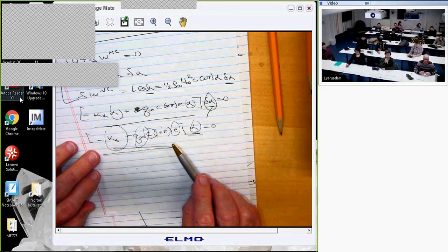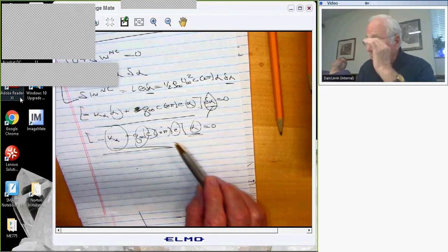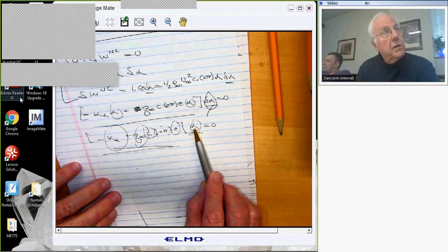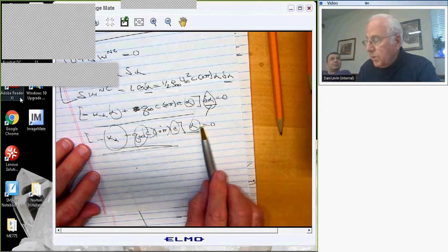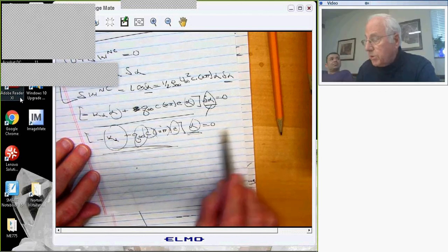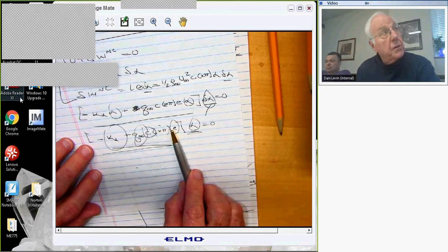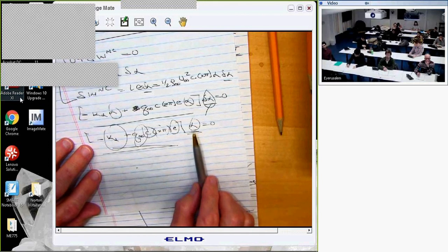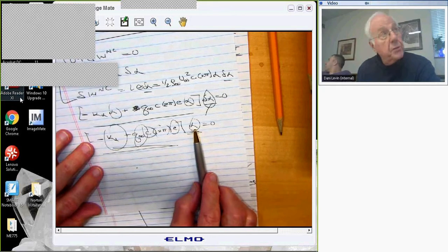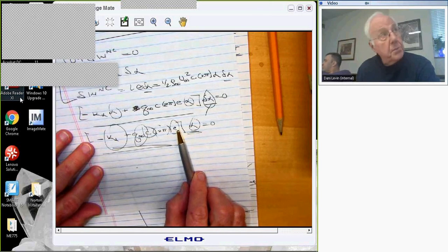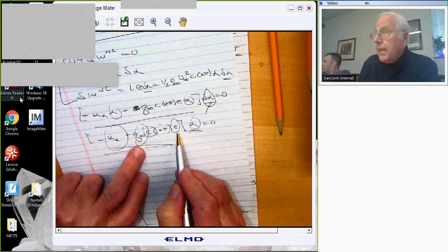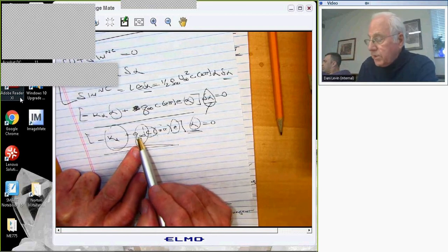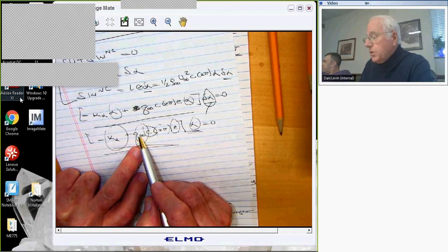What I mean by an eigenvalue problem, an eigenvalue problem is where you have some measure of deformation or response of the system. In this case, it's alpha. And then there's a coefficient that multiplies it. And an eigenvalue problem is when, if you will, the right-hand side of the equation is 0, and there are two possibilities. Either alpha is 0 or the coefficient is 0. And the eigenvalue problem is when you consider the case alpha, or the deformation more generally, not being 0, and therefore the coefficient must be, and therefore you look for a critical value of some parameter in this equation which allows this coefficient to be 0. And from a physical perspective, the interesting parameter is the dynamic pressure. It's the flow condition where alpha can have values other than 0.